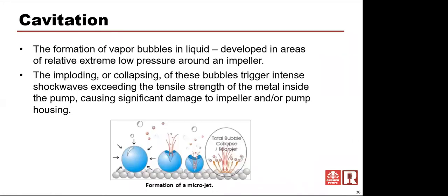Next, we're going to talk about cavitation. If we don't fill those pump vanes well enough, what we get into is an area where this pump is trying to pump water that doesn't exist. And we're going to cause cavitation on the suction side of this pump. I've got a video that I'm going to show you next frame that explains cavitation quite well.